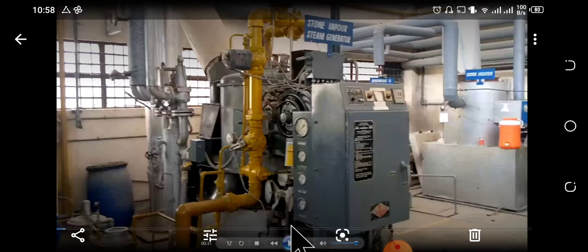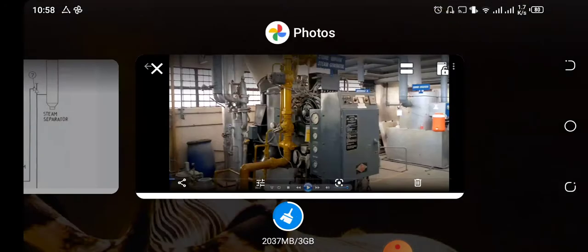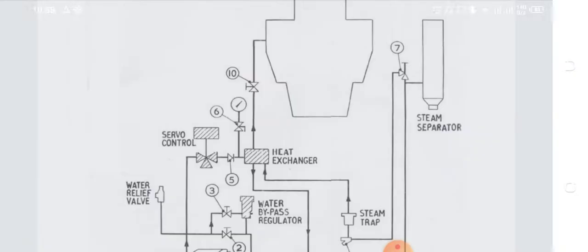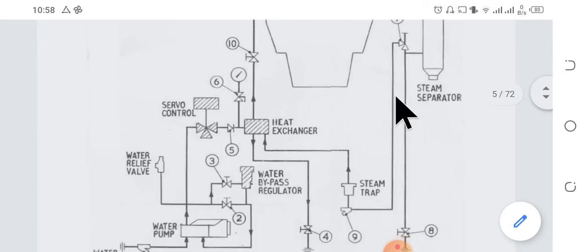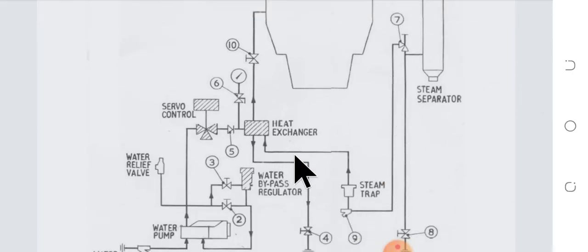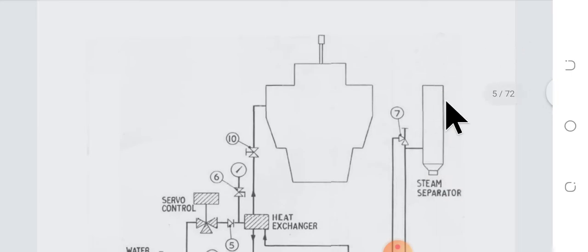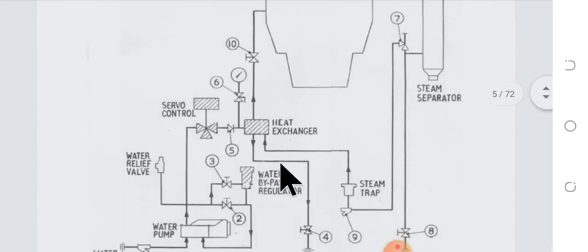Here we have a heat exchanger. In the heat exchanger, basically we are preheating the feed water with our condensate steam. You see that condensate steam. So the feed water is heated with some of the steam coming from the exit of the exhaust steam separator. So it preheats the water, like we have a temperature of 37, and it becomes 86, 87, something like that,